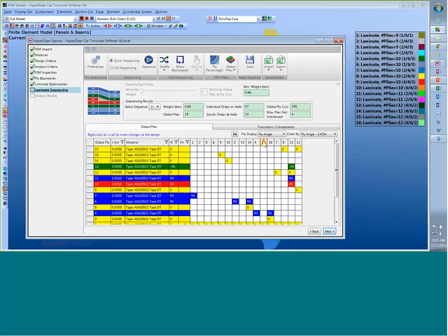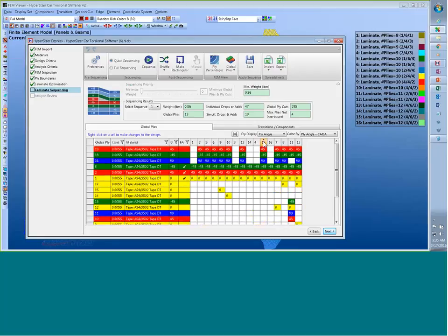If I click 15, you can see that this area right here that has this definition has basically a 0. We'd required 0 on the outside, and 2 45s, a 90, 2 more 45s. So you can see, indeed, it's not symmetric, but it is balanced. So we do have the same amount of positive and negative 45s.